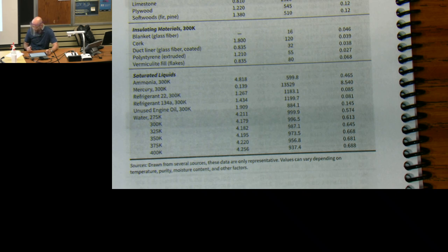Okay, I'm not going to do the algebra here in front of you because it's going to take some time, and I think you can all do the algebra. The temperature 2 here is going to show me it's 46.60 degrees Celsius, okay, and that's my answer. It would have been 319 Kelvin if I would have been doing it that way. So now that I get this answer, I have to think, does that make sense? First of all, 46.6 degrees Celsius means it is still liquid. So my liquid approximation or my incompressible substance model is applicable, so that's good. I know I don't have to go back and recalculate.